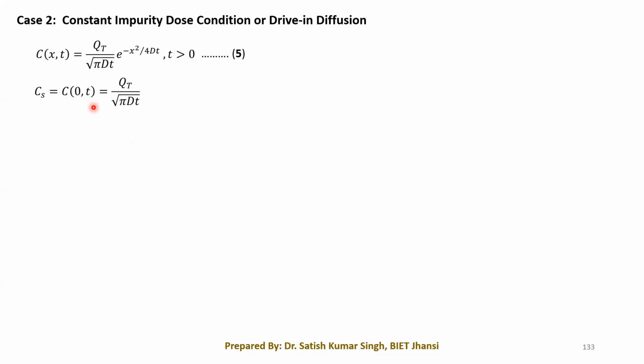Now one thing we can see is that generally the drive-in diffusion time is normally much greater than the pre-deposition time.